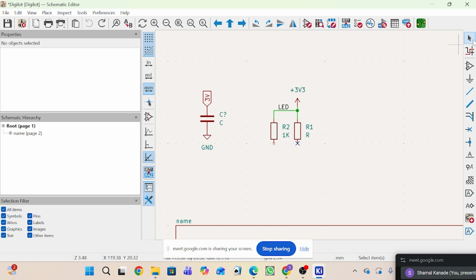Actually, in the microcontroller there is more than one VCC or ground pin. So VCC we connect for the power supply only, right? Using only one pin, there are others. Suppose the microcontroller has four VCC pins. For a QFP package, there are maximum three VCC pins. So in the symbol, they only represent one pin and two pins are hidden in the symbol representation.